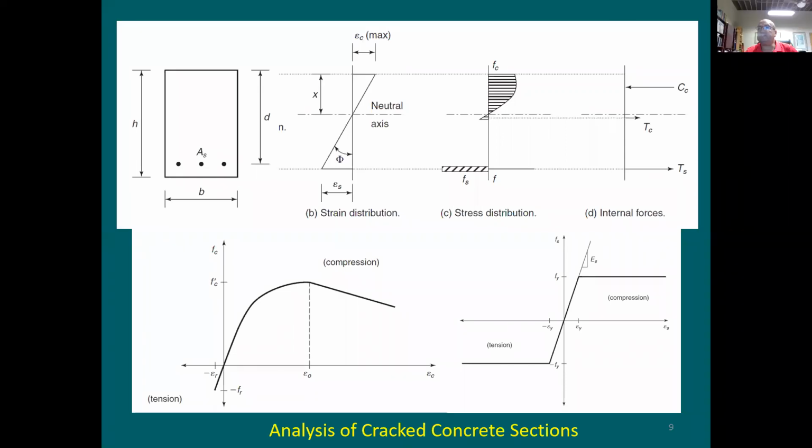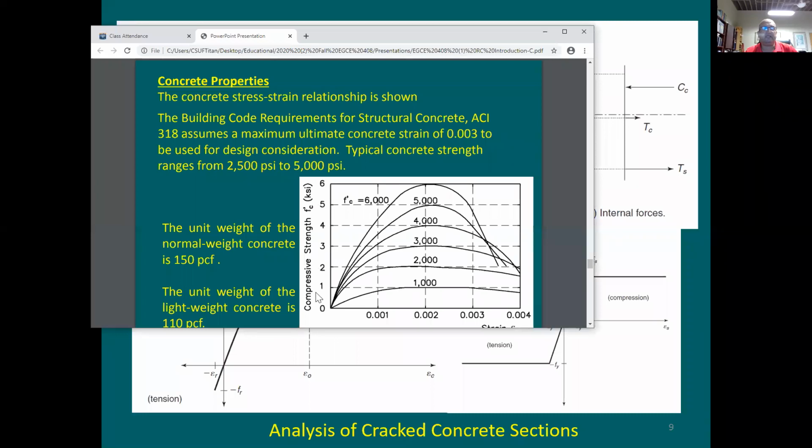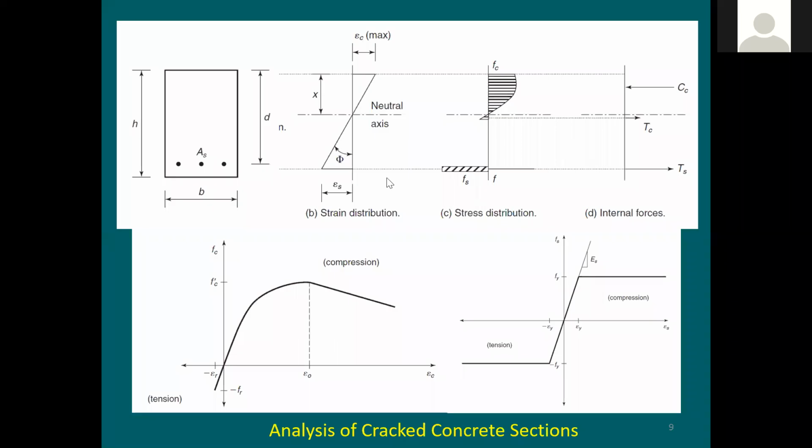And this is the stress and strain relationship that you're looking at. This is actually in compression. It says compressive strength. It is not in tension because in tension it is going to be very weak. It's going to be failing at very small stress value. So I said, okay, understand it's going to be compression. And here the stress is going to be almost equal to 0 at the neutral axis. And right below it,